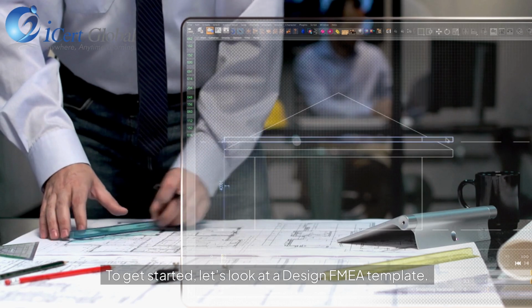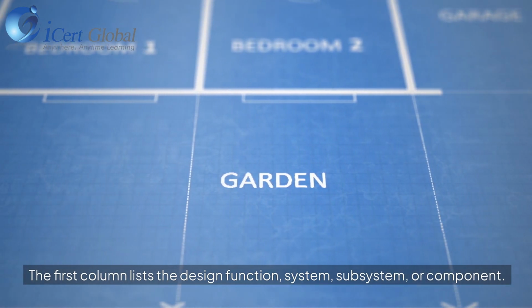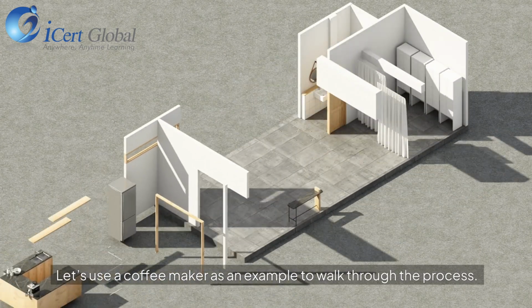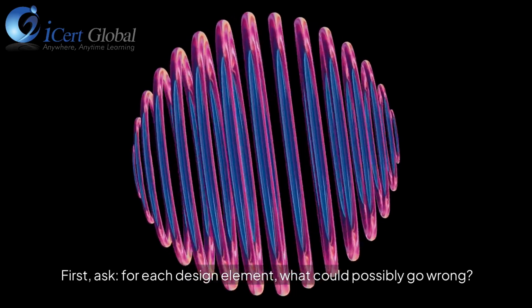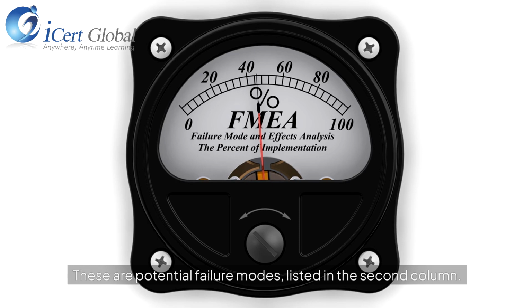To get started, let's look at a Design FMEA template. The first column lists the design function, system, subsystem, or component. Let's use a coffee maker as an example to walk through the process. First, ask, for each design element, what could possibly go wrong? These are potential failure modes, listed in the second column.